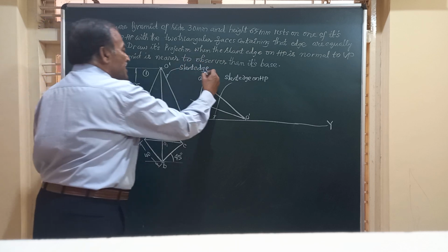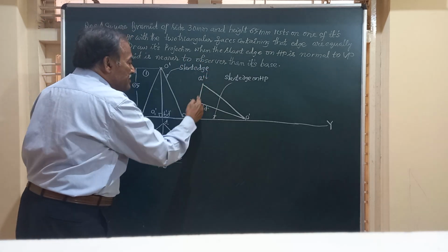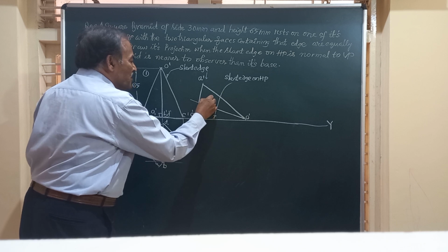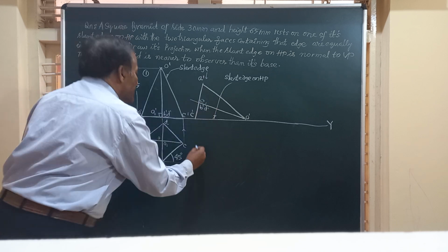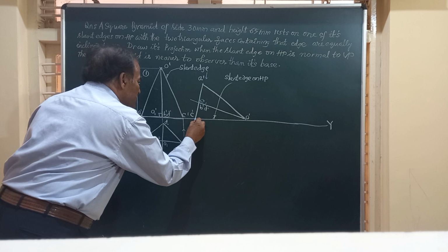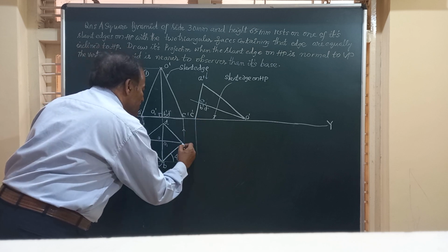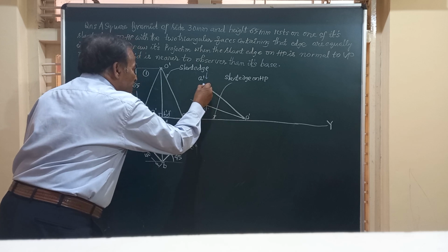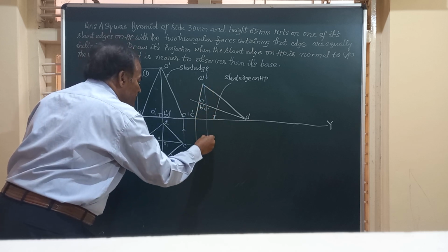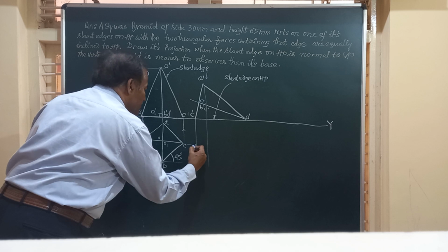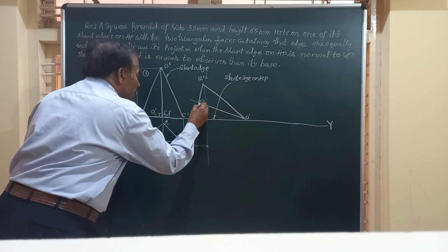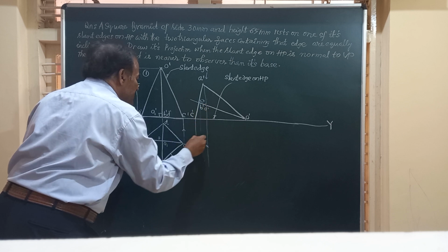Friends, when you see from the top, the complete base ABCD of the base is visible, and hence we will just obtain those points. So on this you will have C, this is point C. On this vertical line through A, you will have the point A on the other end. Then you have this B here passing exactly through the center.